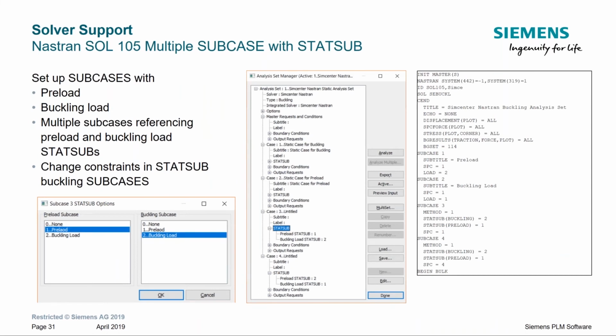We've set up new STATSUB for buckling subcases. So now you could do more buckling instead of doing an individual analysis set for each buckling analysis. Now you can set up multiple buckling in a single analysis set through the STATSUB.